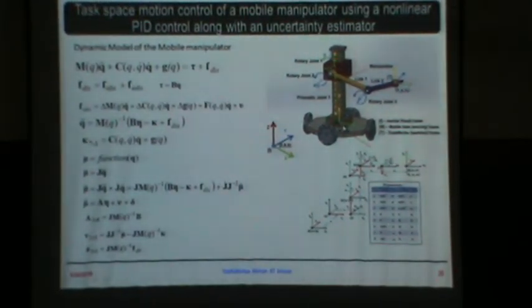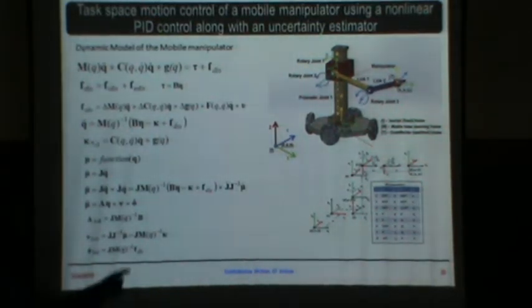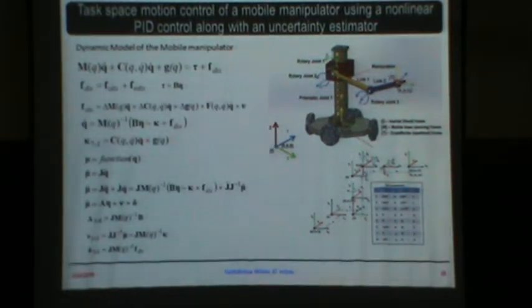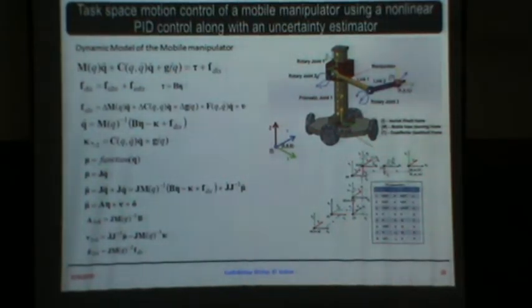So totally like 7 degrees of freedom. Out of this 7, we are trying to get only the position XYZ. Because I can connect any spherical wrist at the end, I can get the 3 more orientations whichever way I want, because controlling a simple spherical wrist is actually very simple. For example, I want to maintain a certain angle in all 3 orientations.